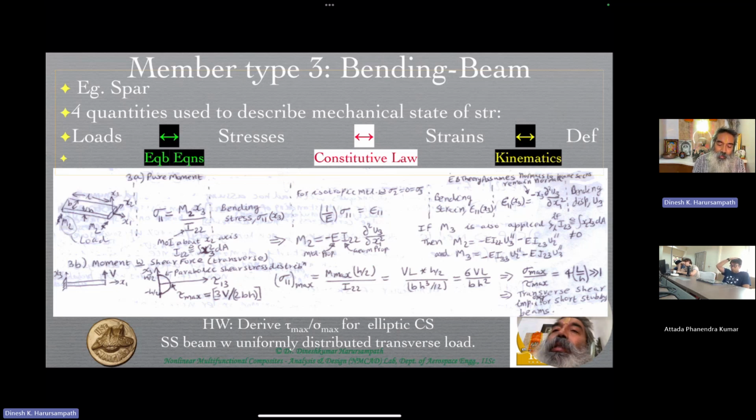So you know that this is something that is much easier to handle, and therefore you still see the advantage of pushing the material outward and putting a flimsier, lighter material in the interior, like a foam or a honeycomb kind of construction. So now you see that where that goes to 0, this reaches a maximum, and where they reach a maxima, algebraically speaking, positive or negative, this reaches a 0.